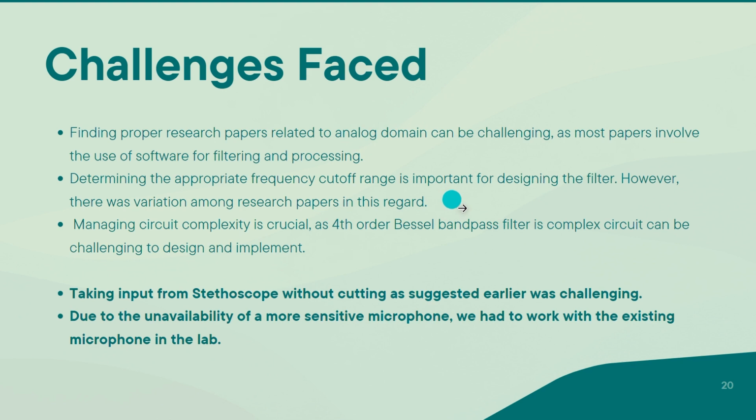Apart from that, since we have to use only the analog circuitry and we were not allowed, we have not used any microcontroller. So finding a proper research paper related to the analog domain only can be challenging, as the filtering stage in most of the papers uses software filtering with a microcontroller. And managing the circuit complexity is also crucial, as a fourth order Bessel bandpass filter is a complex circuit and can be